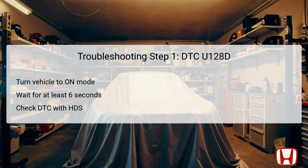Following this, it is crucial to diagnose the DTC using the Honda Diagnostic System, HDS. The HDS allows you to read existing DTCs, confirming the presence of U128D and enabling you to take further steps based on what the system indicates. Proper utilization of the HDS is critical as it can provide insights regarding the specifics of the communication error.